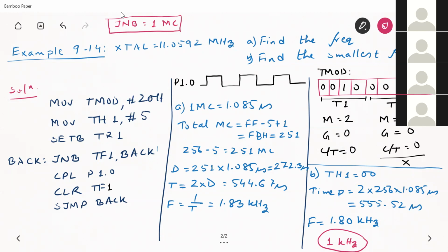Okay, what I'm saying is we can use another loop within which we will put this entire delay, this portion. So we will call the delay a number of times. Over here we do not have a delay subroutine, but we can have one, isn't it? Inside the delay we can incorporate this timer, right? We can simply write delay over here and start the timer, isn't it? Are you getting me? Yes, sir.